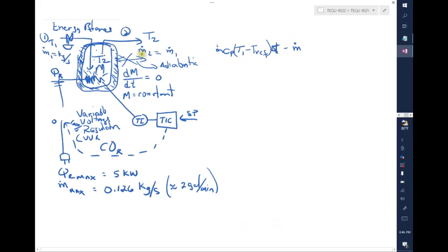I'm going to use the same M because M2 and M1 are the same. Actually, let's write it here just in case. M1, because M2 is equal to M1. Now times Cp, the same material. Remember, this energy balance is done in a fluid, or what we call a single phase. It's not changing phase, it's still in the liquid phase, times T2 minus T reference.